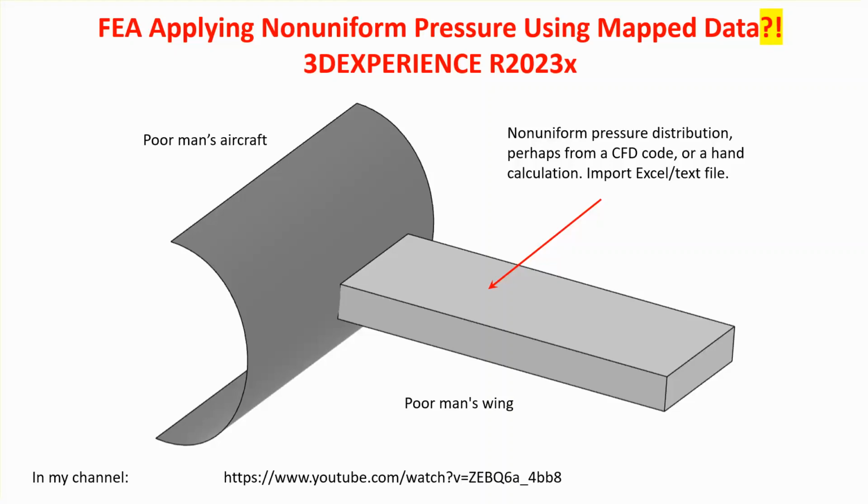Hello folks, in this video tutorial I'm planning to show you how to apply a non-uniform pressure distribution in the 3D Experience FEA solver, which is actually the Abaqus program. Now this comes under the using map data strategy, and when you look at YouTube you see a lot of references for Abaqus CAE where they actually do something like that.